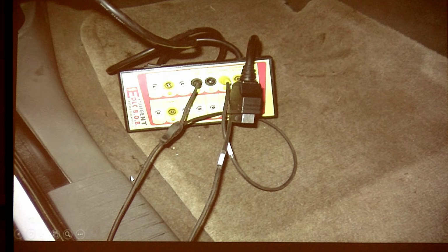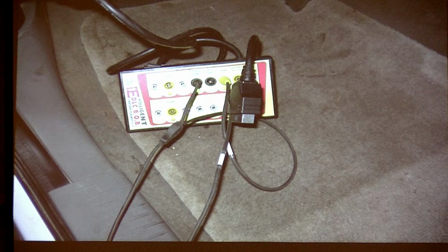This is a breakout box. If you don't got one, buy one. If you don't got this, you're wasting your time. And if you think you're back pinning these things, you're going to ruin the connector so no one's scan tool will connect. You know, we don't back probe these. You don't stab them in the front. Just get someone's box. There's all kinds of breakout boxes. We plug into the DLC.